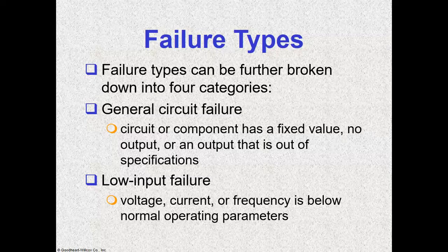It also can be the alternator belt. So it can be the belt skidding, in other words, it is loose. So what other things could we check? What could actually be causing these issues?